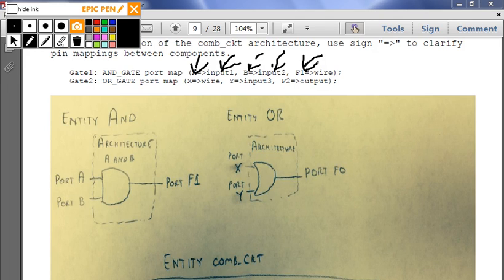So to answer your question, what happens if you map the wrong wire? If you do this, let's say we have 2 wires, we instantiate 2 wires. But we want wire 1 to connect, but for some reason, due to bad code, we have wire 2 written here. It will compile, it will go onto the board, and you'll get an uninitialized or unknown value because it's just taking something from nothing. So that's to answer your question, little brother.